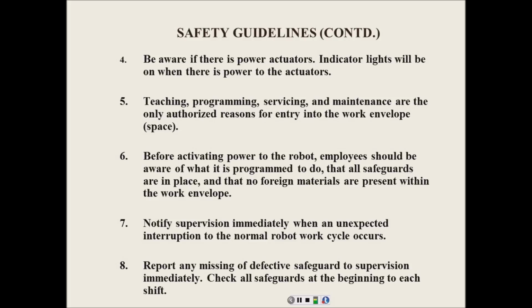If we didn't do that, then aligning the robot, especially the ABB, is not an easy task. It just takes a little time. But here, all we have to do is just re-origin the robot. Then we can put new batteries in there, or use it that way until we can get new batteries. That's why we like the FANUCs. The small FANUC, 200iC, uses alkaline C batteries. The big FANUC uses alkaline D batteries that you can get anywhere. All the other robots use proprietary batteries, so that's why they cost more.